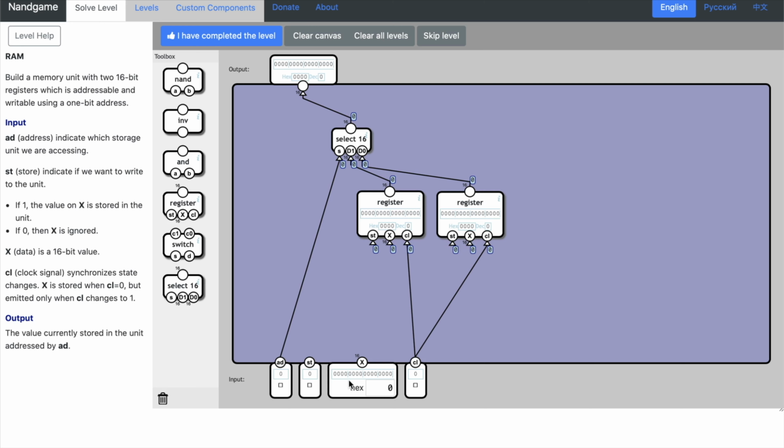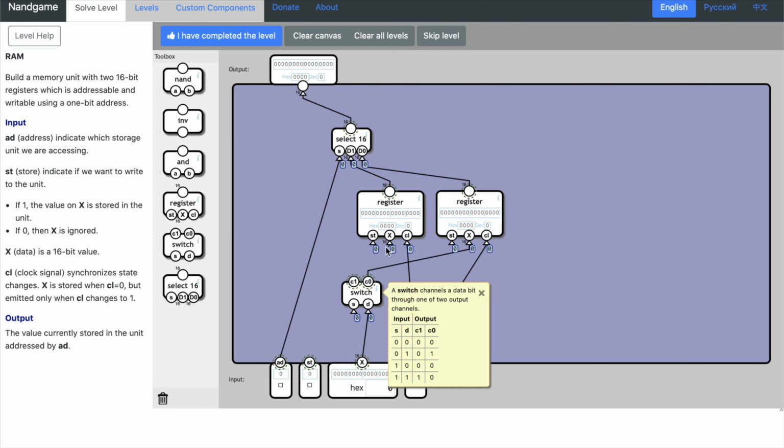What do we need? We want to store X in the register that is selected, but equally, unlike the other one, we don't want to store X in the other one. We don't want to overwrite the value of a register. So in this case, I think we need a demux, where this X value is the data in the demux, and that is destination 1, or destination X, and that is destination Y. And that just leaves us with this switch. And again, I think it's... no, I think I've messed up. This does not seem right to me. This is not going to work.